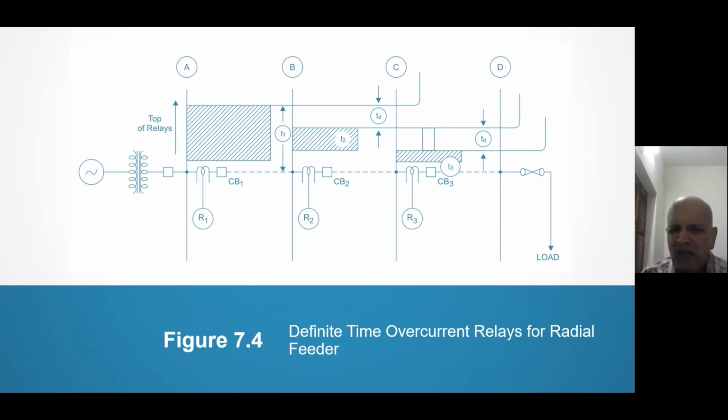So my dear friends, power system protection is a very logical subject. If you are sound at logic, then you will understand. Here, the transient overreach problem is not there. And when I am making relay R2 reach up to D for the least fault, the double line fault, then for a triple line fault it will certainly reach because the current is more.